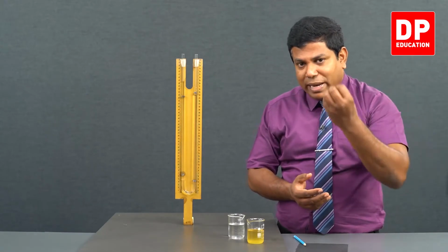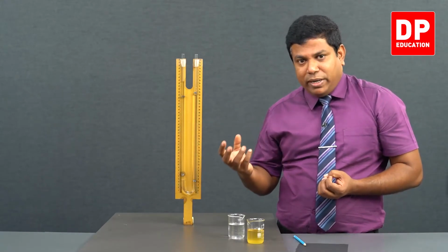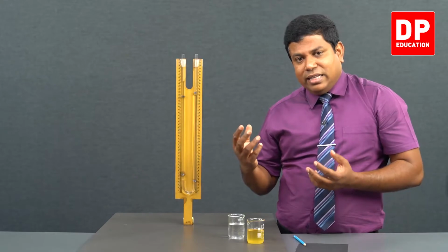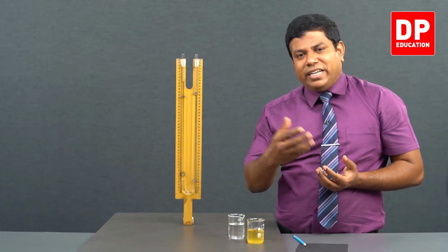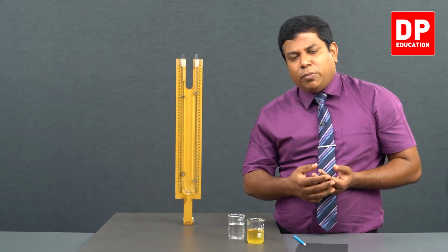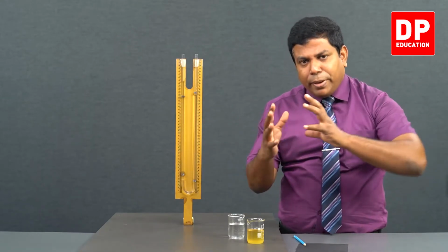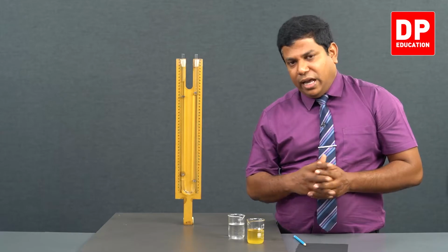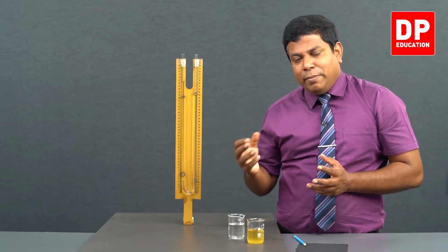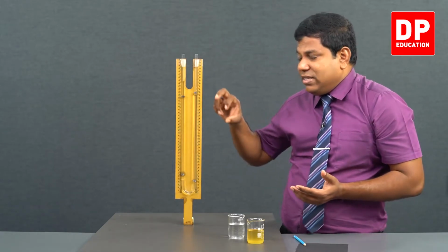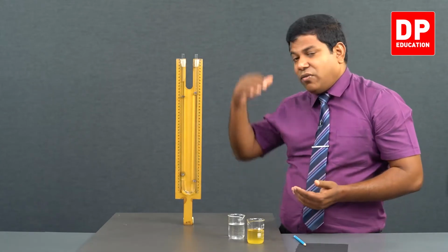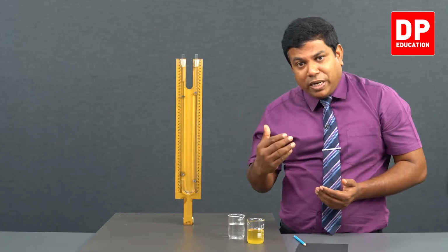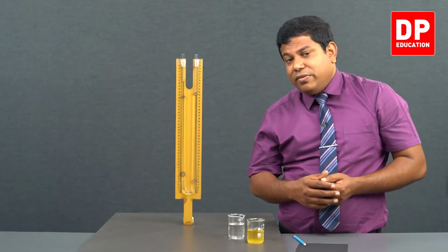So that is one of the main difficulties we have with this experiment. The relative density must be somewhat close to 1, say 0.7, 0.8, 0.9 or 1.2, 1.3, 1.4, a somewhat comparable range. Right? Otherwise, you will not be able to do it, because the difference in columns will be vastly different. Then the height of column you need to do the experiment and get 5 readings will be difficult.